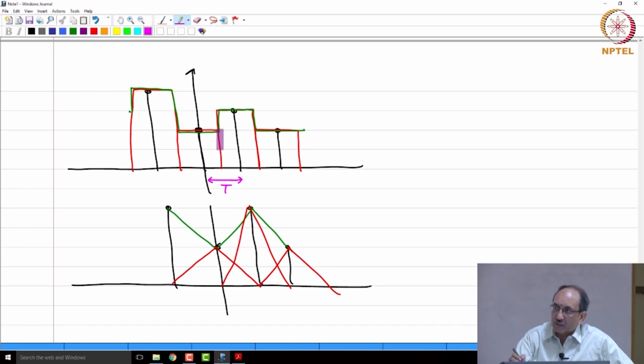So, this is better than the previous case because you require a less stringent low pass filter, but again there is no free lunch. To have come up with a filter that is like this requires more processing. But if this is all done in the discrete time domain, it is simple, but we have to do this in the continuous time domain. So, you need to come up with a filter that has this kind of impulse response, and then you will reconstruct. Rather than sinc interpolation, you are doing either sample and hold, which is interpolation using this kind of filter, versus this kind, and this is better. And this is what is fed after you take this, process it through a low pass filter and then feed it to your speaker. So, this is how reconstruction is done.